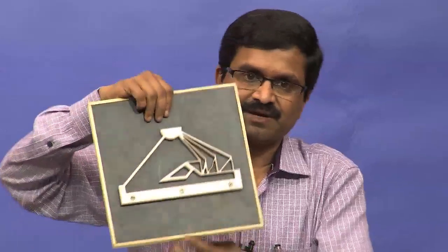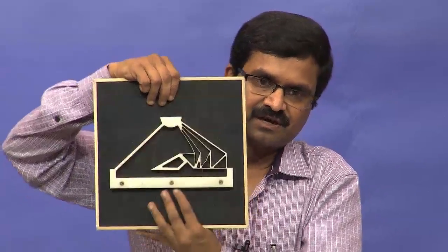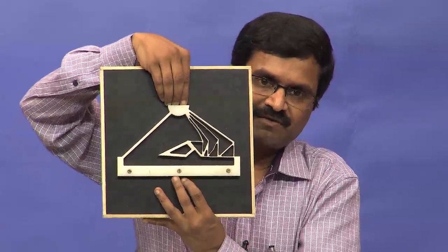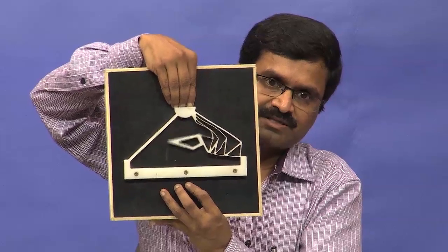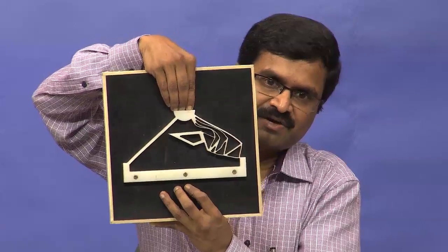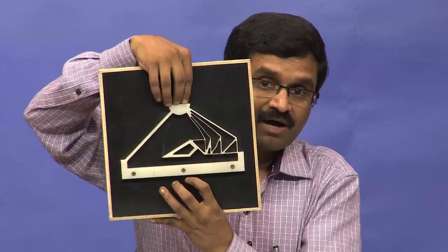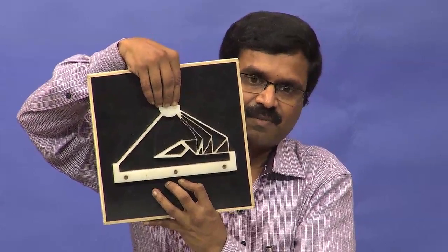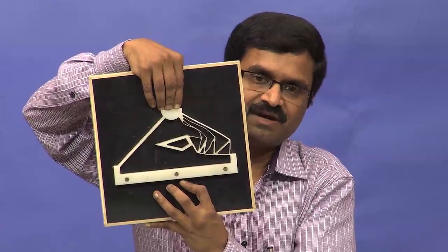Okay. And here is another device. This is also a displacement amplifying compliant mechanism, which is fixed over here. This entire piece is fixed, screwed onto this board. When I apply force downwards, this thing moves upwards by a large amount, right. When you hold it in your hand, you would feel that there is large displacement and large rotation, but very little strain, and even if you do it a billion times, this device is not likely to fail.